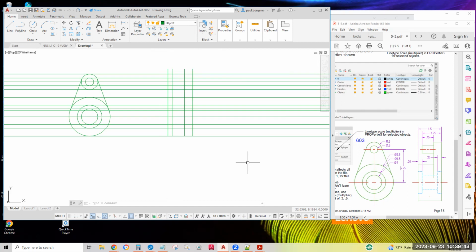Okay. I'll later erase the guidelines here by selecting across the top, and I'll erase these, my crossing windows, select them all there. So it's kind of risky using the same layer, but I'll start the line command and click around and attempt to do all the green lines of the right view, starting there, straight over to that intersection.